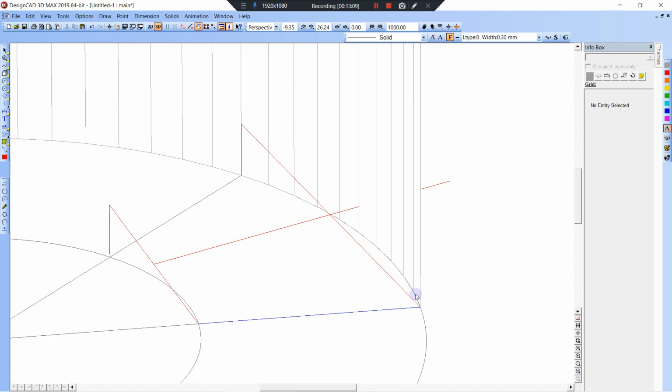It would be pretty easy in the field to measure, if you're measuring from here to here, get a pretty good center. And it'll be very close to the center. What happens sometimes you're on sloped ground, the ground's not level, but you could pretty much find the thing here by just swinging 2 arcs. If this was flat ground, you could swing 2 arcs, and the center of those 2 arcs would give you the middle, and that would line up right with this spot.